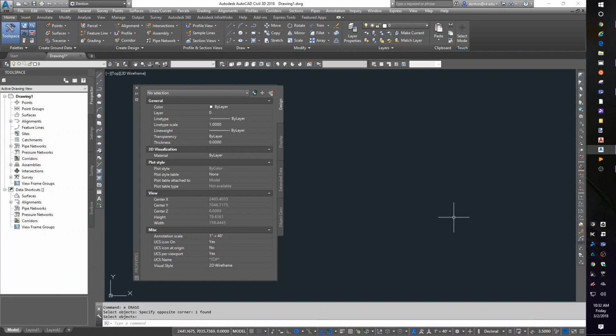Circles or fillets. Let's say I have a line here and I have a line here, and I want a 250-foot radius between them. The fillet command, fillet radius 250, pick the line, nothing fitting. Okay, it says my radius is too large.